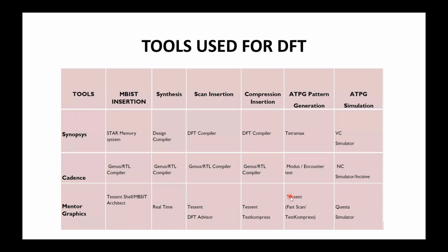ATPG will also use Tessent TestCompress, and simulations will use Questa. For synthesis alone, we will use Design Compiler, the Synopsys tool. Synthesis is actually not part of DFT, but we need to do synthesis at one stage.